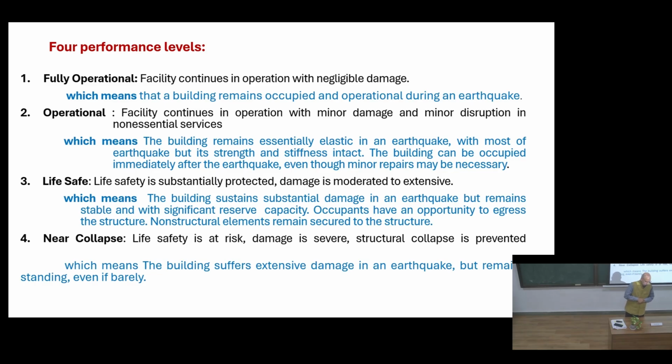Most of the time in practice in a building, if you make a roof, suppose the required thickness is 4 inches, 100 millimeters, people say 150, 200, 250, because you have added more strength to the floor. Okay? What about the column, the supporting system, the vertical members? If you squeeze the size, what will happen?